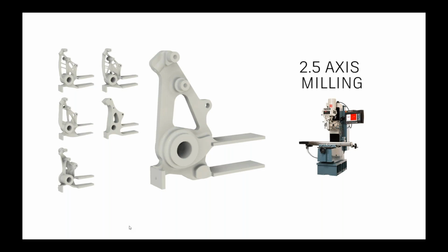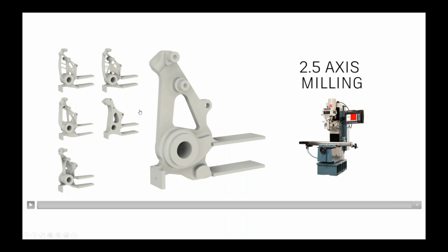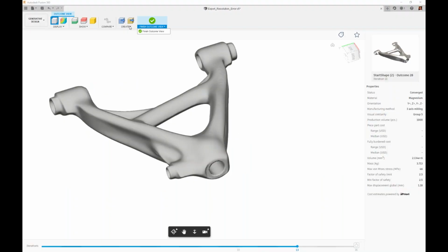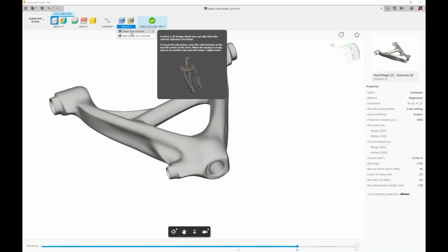Oh, you taking that one, Mike, on fatigue? Oh, sure. I was going to type it in, but we can answer it live real quick. The short answer is that within the generative design environment, fatigue would not be considered. But if you export this to the simulation environment, it will import your constraints and your loads, certainly editable, and the material will be imported.